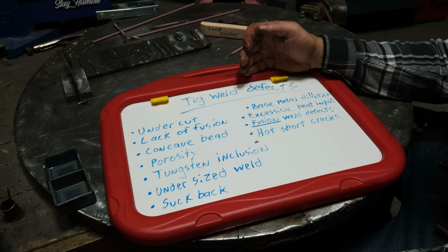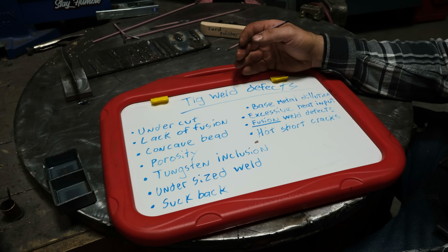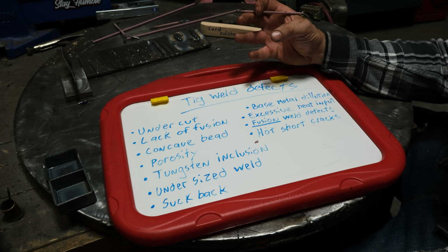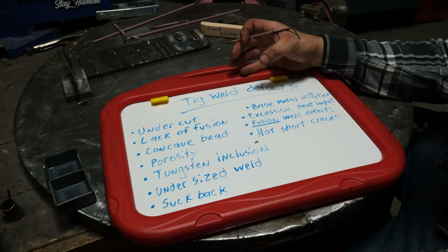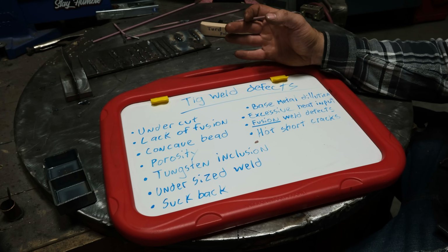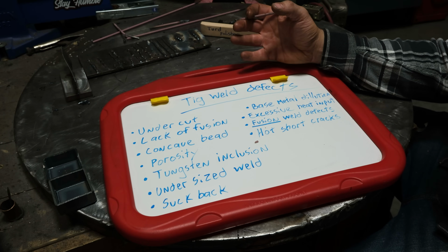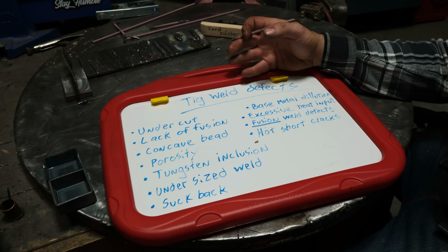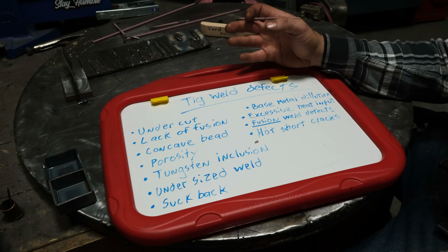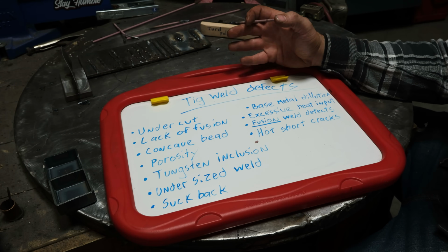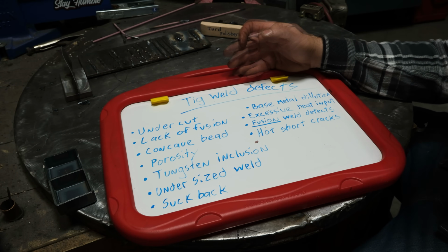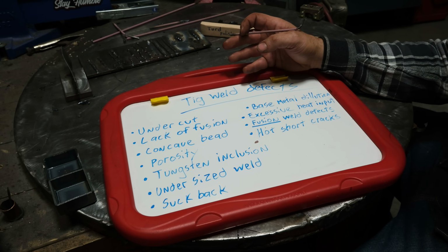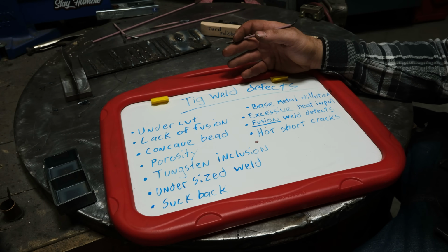One is you're going to have a lot of warping. You're going to probably have more issues with undercut. The grain structure of the solidified weld itself will often be subpar, as you're cooking the weld, not just on stainless. A lot of people think that cooking welds is only an issue with stainless. No, it's also an issue with steel. And that's why I'm a proponent against fusion welding over a weld.